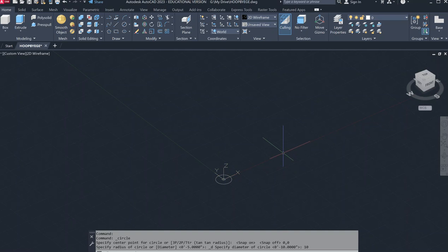Okay, now I need to draw a vertical line to this plane in the Z direction. But one of the interesting things is, from a practicality point of view, the computer is more comfortable generating on the XY plane. So I want to change the XY plane so that I can comfortably draw my lines on the XY plane.